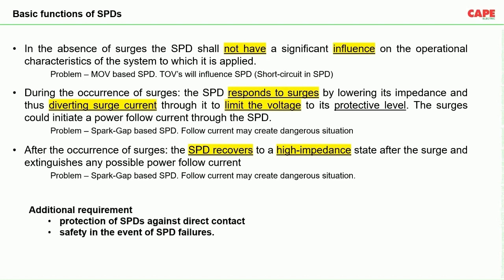So additional requirements have also been specified by the standard IEC 61643, Part 12. First one is protection of SPDs against direct contact. That is very obvious. That means once an SPD is installed, we should not be able to directly touch the current carrying parts of the SPD. That protection we have to provide.